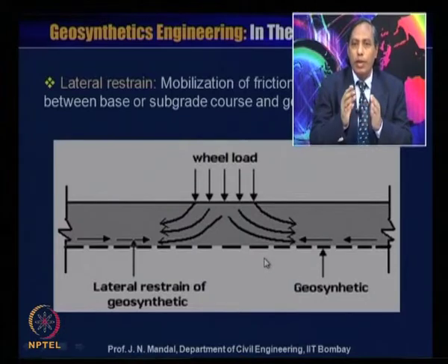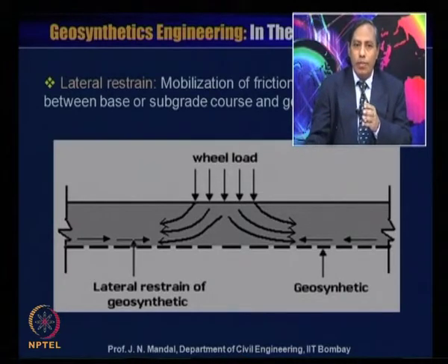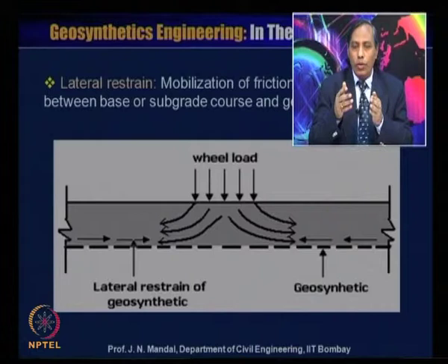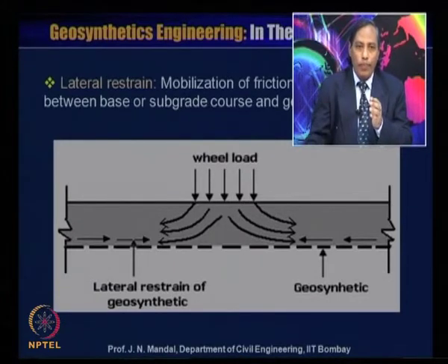So, due to the wheel load, there is a mobilization of friction, or if it is a geogrid material, there will be interlocking or bonding between the base course and the subgrade course and the geosynthetic material. So, that is why that lateral restraint mechanism is important to us.